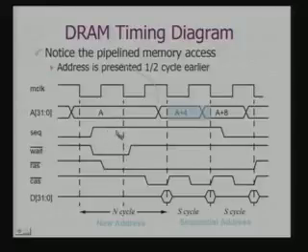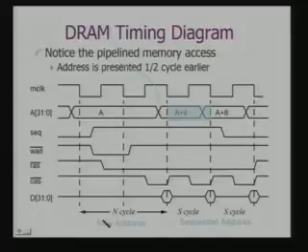So when it knows that there is a sequential access, the wait need not be low. RAS remains valid all through, and you are asserting CAS with different column addresses, so you are getting the data from consecutive locations. And this is precisely the reason why the ARM processor core provided SEQ as an output signal. But you can understand that to use these signals for actual interfacing, you need to implement the interfacing logic.